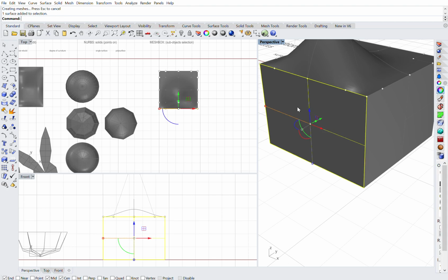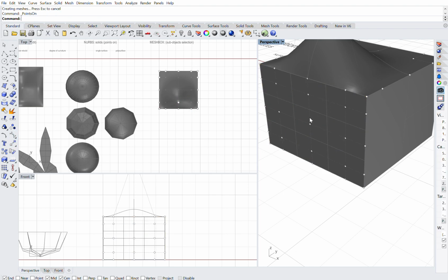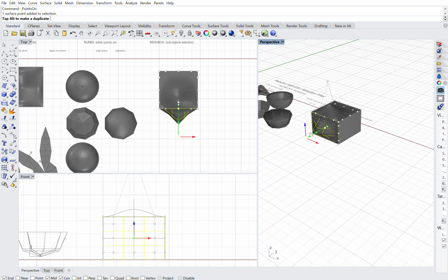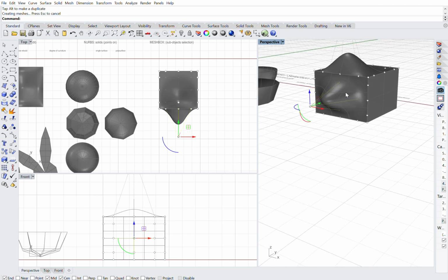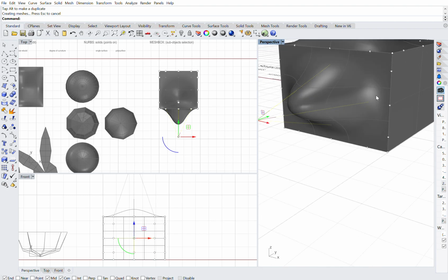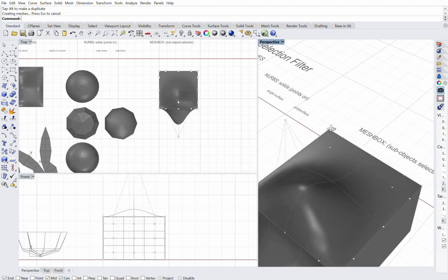And again, rebuild. Remove the curvature, maybe make it 2. Turn on the points. Let's do some tests. Okay, so it's less curved, still quite dynamic, and as you can see, the points keep certain parts of it in place so that it's still a solid object.